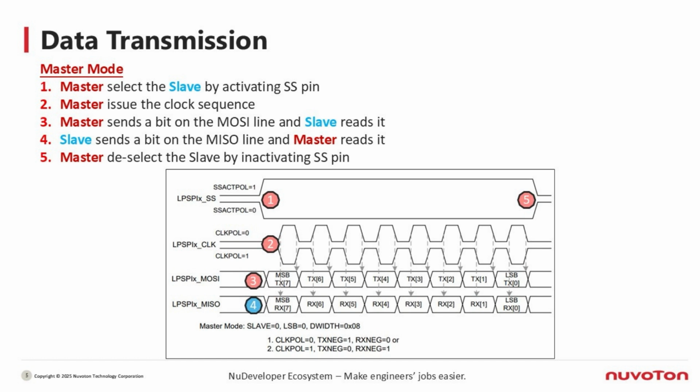At the same time, the slave also returns data through MISO. The slave usually pushes data out on the opposite clock edge, and the master samples it on the configured receive edge. Again, it's 1 bit per clock, and by the end of the sequence, the master reconstructs a complete byte.